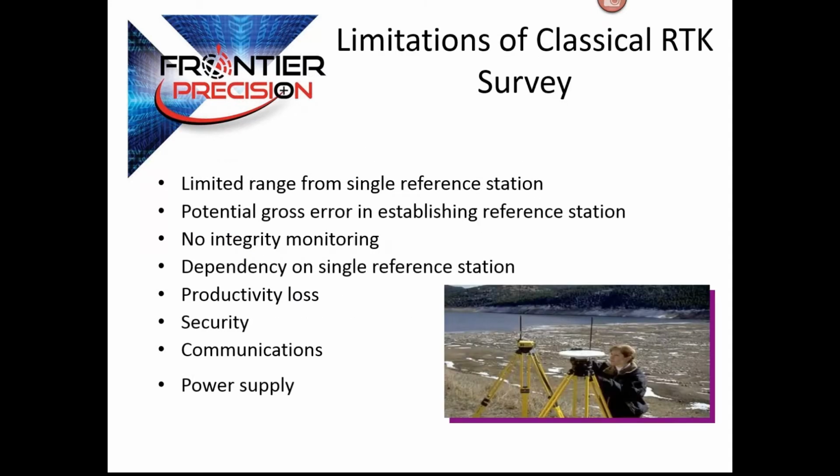So if we used to do that, there were all these limitations of classical RTK surveys. There was limited range from a single reference station, and more so today because of narrow banding. We have a webinar that was done on the impact of FCC narrow banding on RTK usage, and I would encourage you to watch that. But also the potential gross error of establishing reference stations,